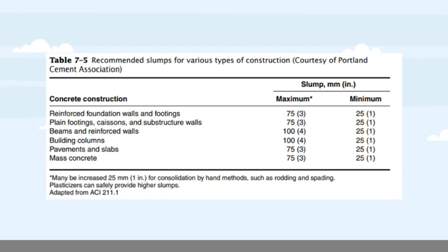Of course, the next step is mixing the trial batch using a convenient quantity of cement at the selected water to cement ratio. Then we add quantities of saturated surface dry fine and coarse aggregate until we reach the desired slump we chose from Table 7-5. After weighing each trial, the yield of the mix and the amount of each component required for a full-scale batch can be calculated by the method I will discuss later.